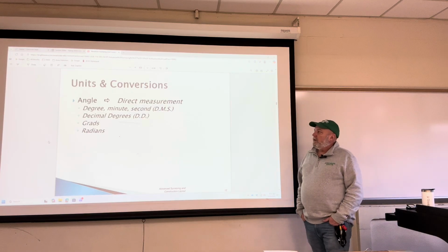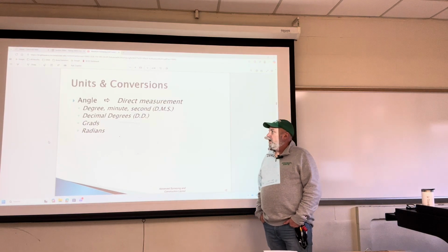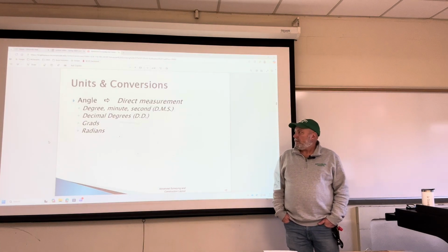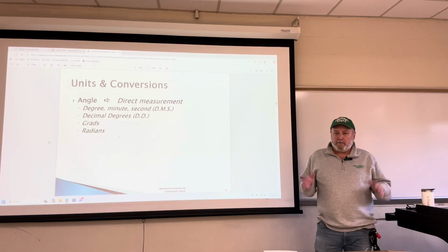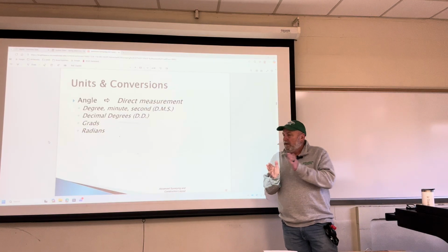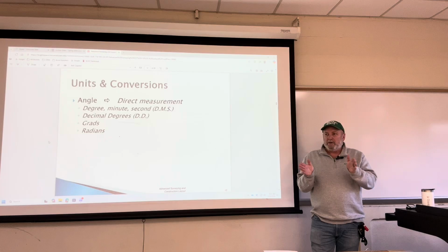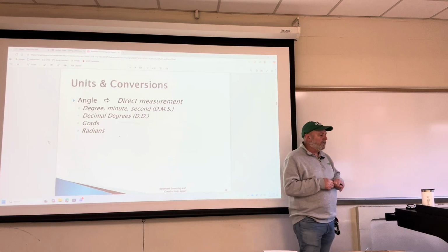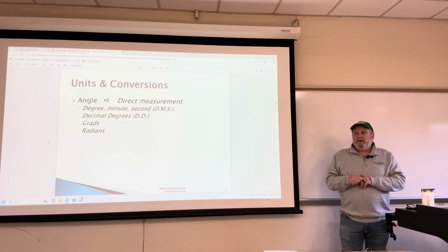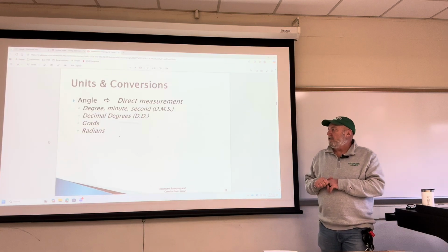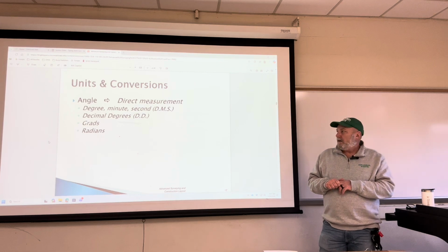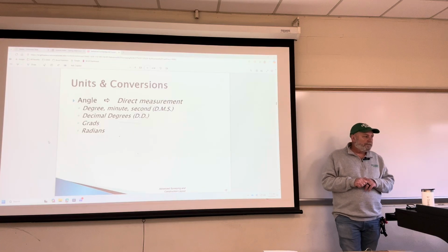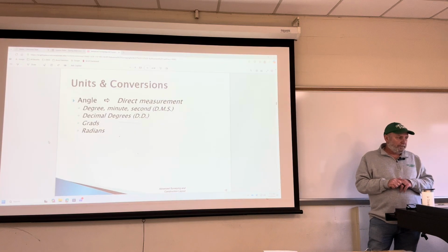We also do deal with decimal degrees, and typically that's done if you're doing any calculations out in the field. It's a lot easier when you've got a couple bearings and you need to know what the angle is in between. It's easy to convert those bearings to decimal degrees, do your adding, subtracting, whatever, and convert it back to degrees, minutes, seconds. We will touch on this, the longhand version. However, I'm a big fan of using the conversion on your calculators for it.